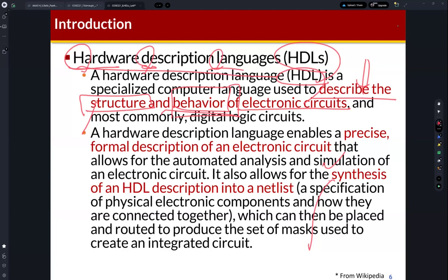You need to remember and understand this. In software, if the result is correct, then it's okay. But in hardware, even though the result is correct, the synthesized hardware may be incorrect. So we need to focus on the synthesized result, because this is the purpose of hardware description languages.